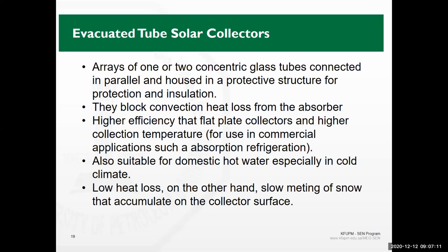But why evacuated? The reason is, for evacuated tube, vacuum means no medium. So there is no energy loss from the collector to outside by convection. So basically, you are maintaining your fluid inside at a higher temperature. And evacuated tube collectors are the ones that are used whenever a slightly higher temperature is needed. If I'm talking about a flat plate collector, that can heat water up to 70 or maybe sometimes 80 degrees centigrade, so going above 80, maybe to 120 or so, this can be done by evacuated tube collectors.